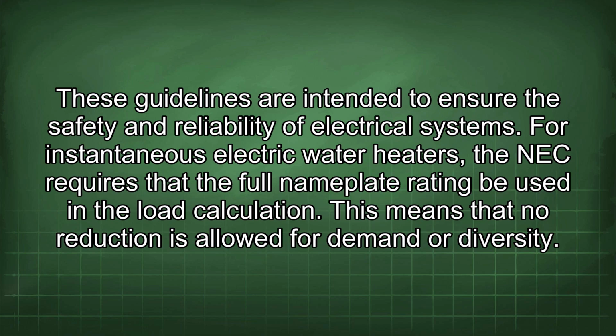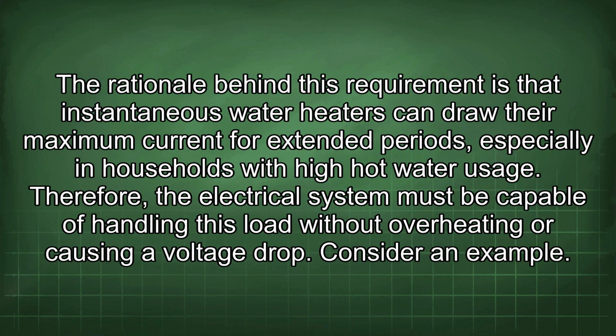For instantaneous electric water heaters, the NEC requires that the full nameplate rating be used in a load calculation. This means that no reduction is allowed for demand or diversity. The rationale behind this requirement is that instantaneous water heaters can draw their maximum current for extended periods, especially in households with high hot water usage. Therefore, the electrical system must be capable of handling this load without overheating or causing a voltage drop.